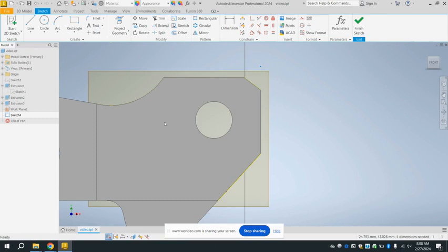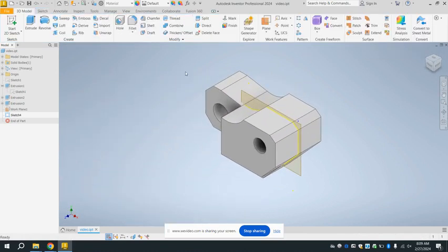There, now that that's deleted, we can begin to make the indentation. But first, before we make the indentation, we have to make sure we make this a complete and closed shape. Otherwise, it won't extrude. So what we can do is just go to project geometry, select all of these sides, and that should count. Once we're done with that, we can just finish the sketch.